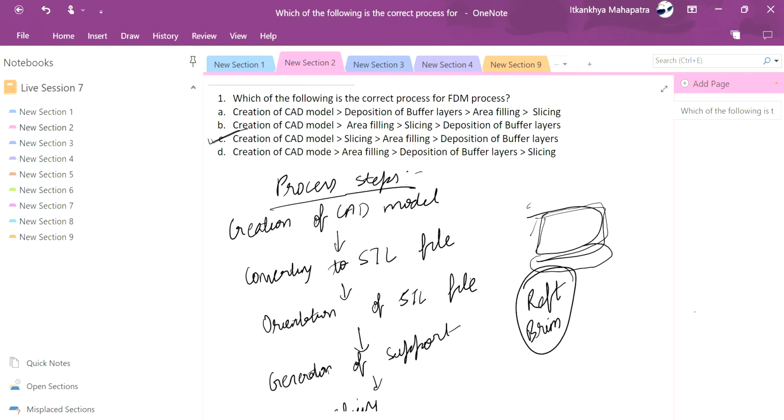When printing starts, the printer also lays down a little additional layer so that any unwanted filament coming out of the nozzle is removed. The raft is the additional layer below the specimen, given so that when you remove the specimen from the 3D printer, your sample won't get damaged. That is the advantage of the raft. It also gives additional strength and support.